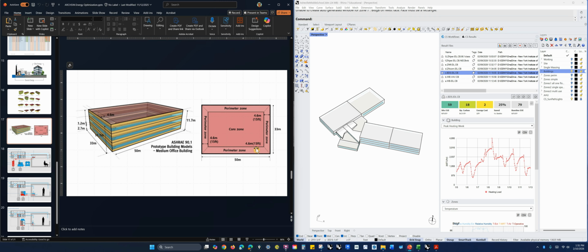Once you're heating and cooling these 4 perimeter zones, the core kind of becomes the same, right? If you're not thinking about how many people are in there or how much equipment, because it's buffered by these 4 zones. So it becomes this buffered ambient zone that's going to have a different thought process in terms of how you're going to heat it and cool it. So that's the idea behind this.